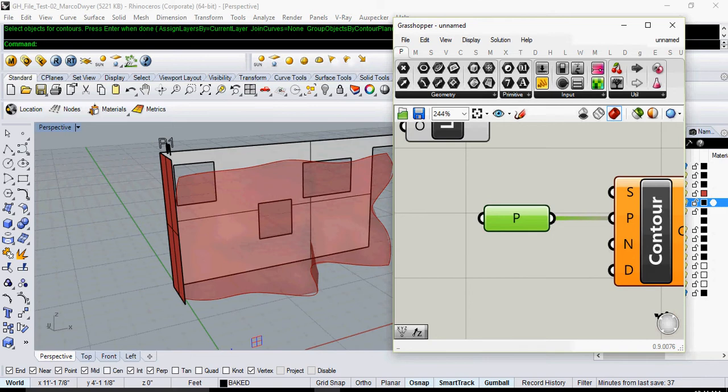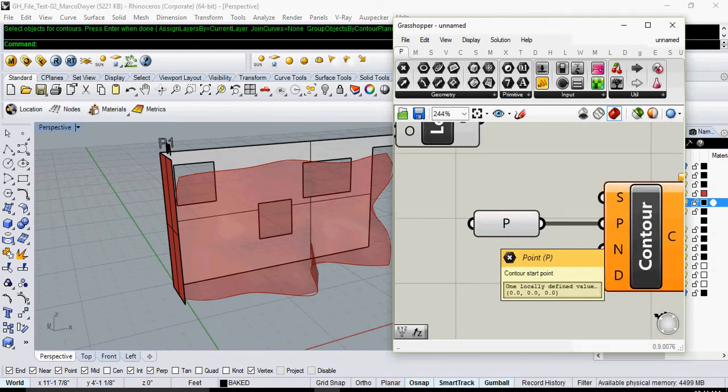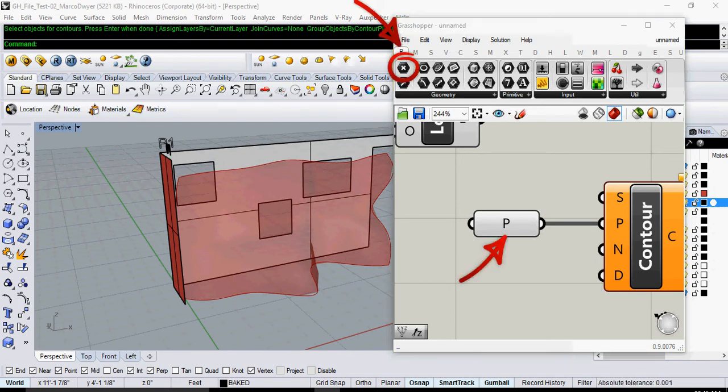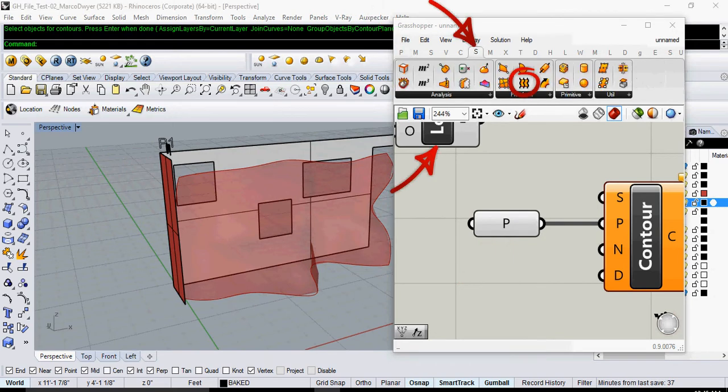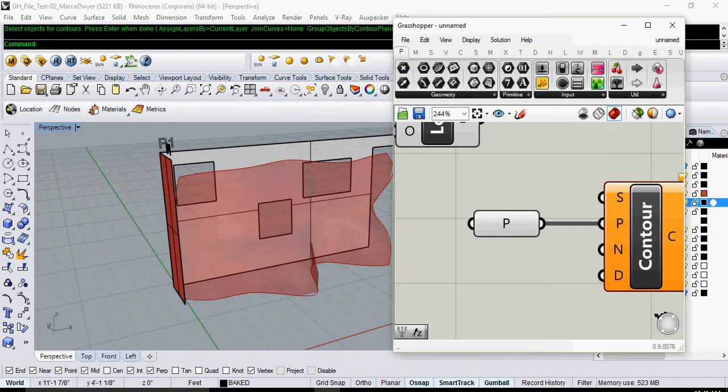And you can actually right click and set multiple points, but what's more important is, if you hit Control and Alt at the same time and click on this node, Grasshopper will show you where it's located, and that works with any case. So it's pretty cool. You can find what it is, and you can go here and figure out what it wants. So a point wants a collection of points.